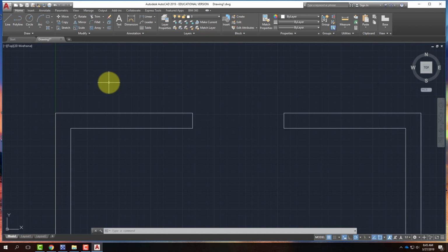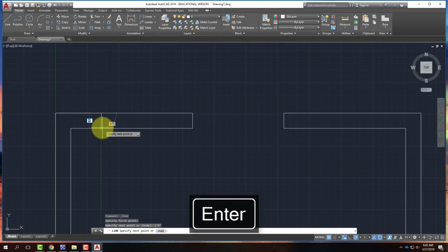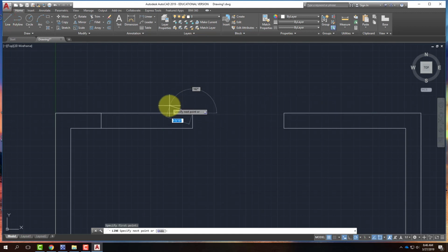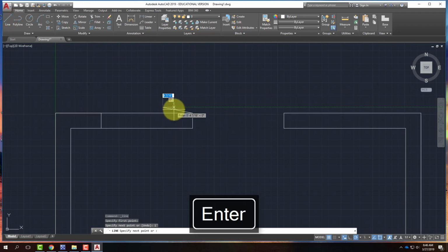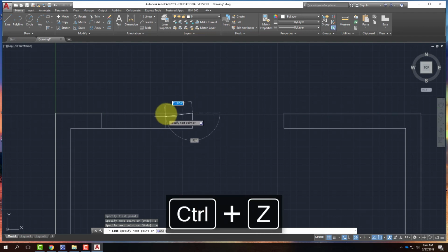So when it comes to placing this window, remember I said it's 1'6" from this corner over, and it's 1 foot from this corner over. Typically, people will go ahead and just draw a line, and they say, OK, that's great. I'll go over 1'6", and then I'll come down to right there. I'll press Enter. All right, I've got that line. And then I can do the same thing. Start here. We'll draw over by 1 foot. Oops, sorry, my mouse moved.